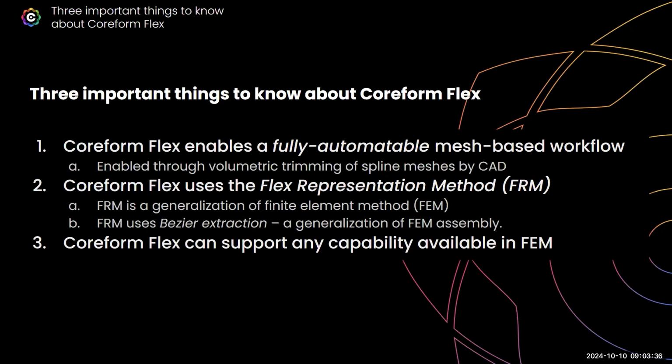So it's important that today we support traditional CAD BREP models, such as a STEP file. Coreform Flex uses a technology that we've developed at Coreform called the Flex Representation Method, or FRM. The important thing to understand about that underlying technology is that it is a generalization of the finite element method that is based upon a core technology called Bezier extraction, which itself is a generalization of the finite element method assembly process.